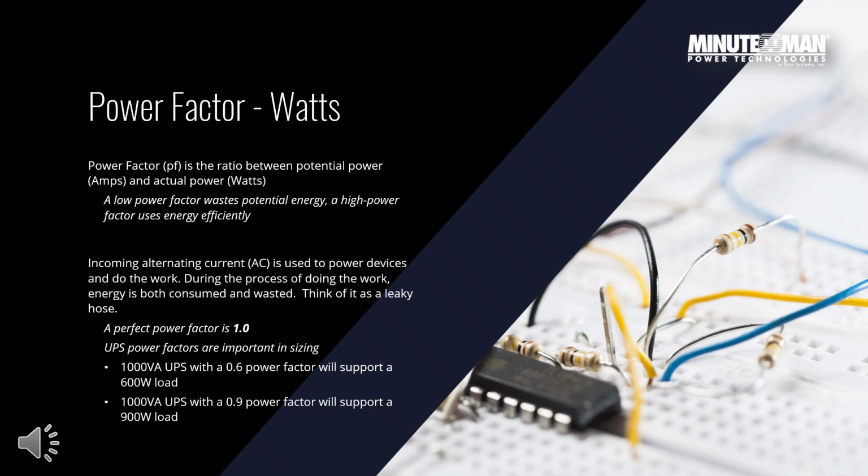There are three types of power in AC circuits. Real power does the actual work. Reactive power does not do the work but is necessary for maintaining voltage levels used by motors or transformers. And apparent power, the combination of real and reactive power. Think of apparent power like a beer. The whole mug is the apparent power, the whole beer. The foam on top is reactive power, and the beer is the real power, i.e., how much beer or power you really have.